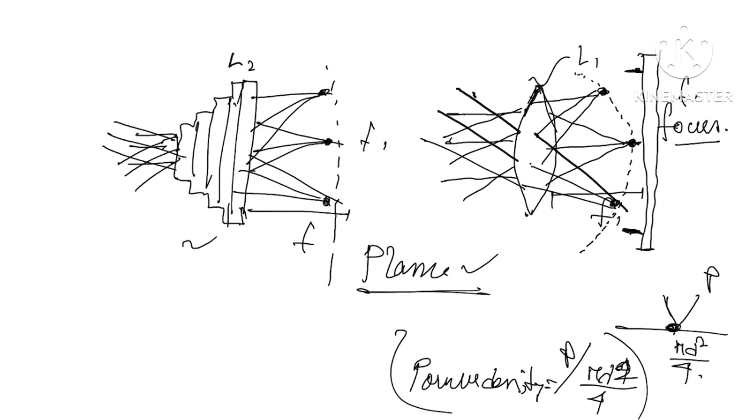But here, if this is the focus point and the laser beam is falling at this position, this is the defocus region, or this is not the focus spot. So the laser spot diameter will increase. As a result, the power density will decrease. So we cannot get a constant power density over the build plate, over the whole powder bed. This is obviously a disadvantage of using a normal lens.